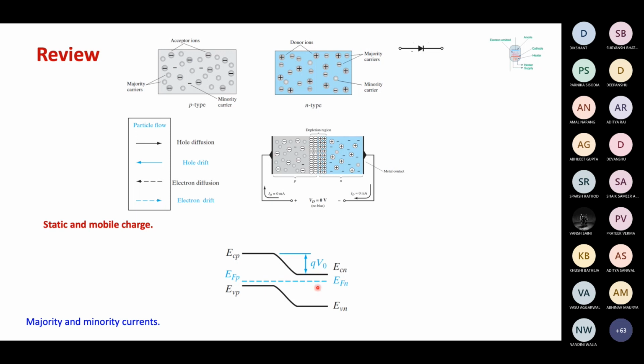No, I'm not going to the p-type right now. What I'm saying is, if the Fermi level is closer to EC, electrons will be more in n-type and holes will be less in n-type, in the same material, okay? The minority and majority carriers are inversely related to each other in any semiconductor material.